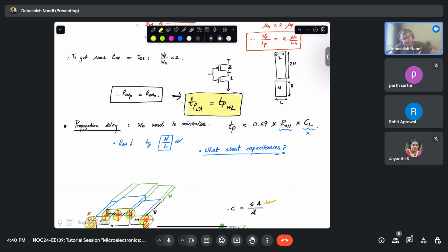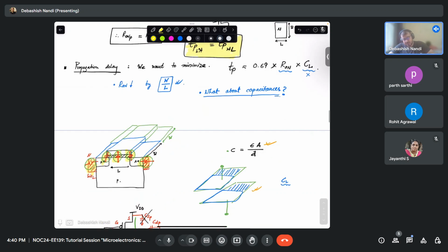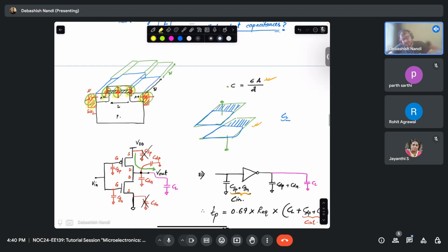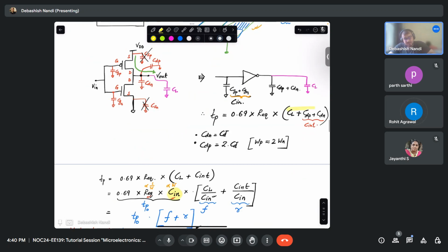This is another key point. Then next point is you need to understand this equation, capacitance. The internal capacitance will start to add on to the load capacitance. So this will come in parallel with CL. So all your charging and discharging will be through this entire thing, the parallel combination, because this also you need to start to charge.